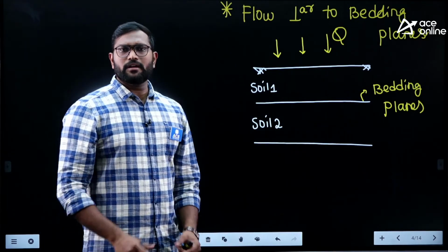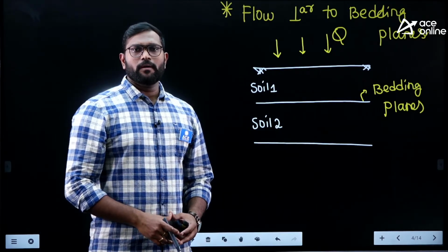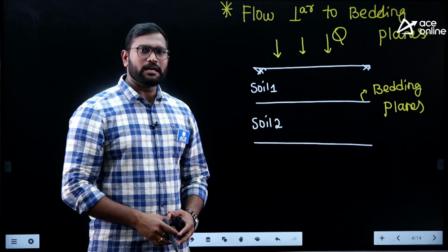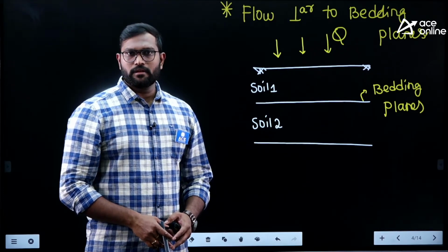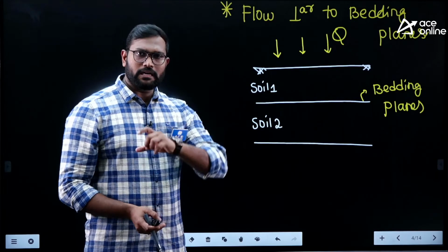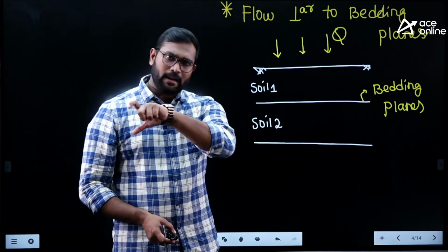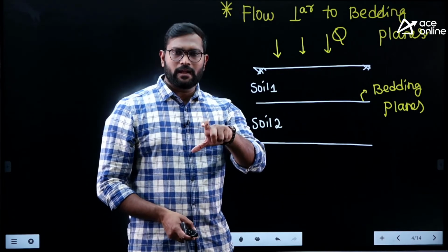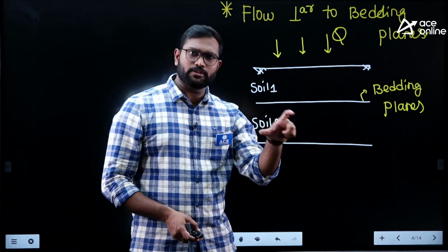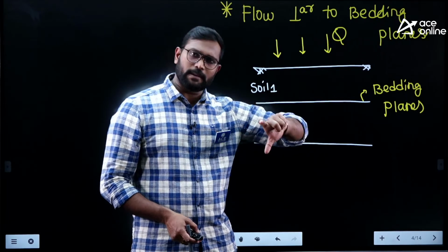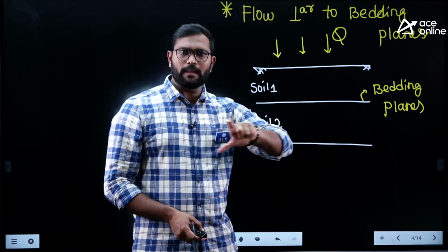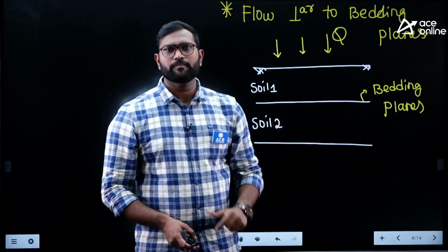Does it just look like flow in pipes connected in series? Flow in pipes connected in series. So you release some flow rate that will pass through pipe 1, and pipe 2 is connected in series, so it passes through pipe 2, and pipe 3 is connected in series, so it passes through pipe 3. In all the pipes the flow rate is the same.